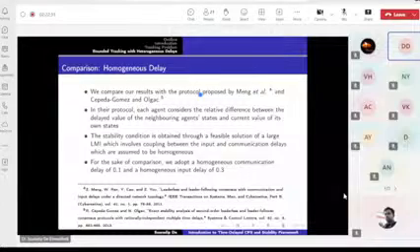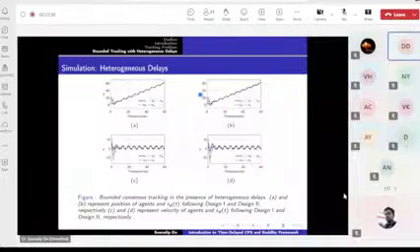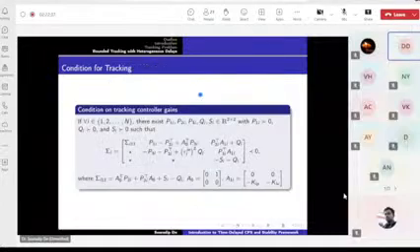So if you go here, what we have done for the LMI in this particular case: you can see here the LMI I am doing is for the tracking controller gains only. For the tracking controller gains, I am considering the individual agents only, not the complete system. Let's say I have these double integrator agents, that means it's a second order system. So I don't have to account for n agents, 20 agents. The advantage of this is that I don't have to deal with big, large LMIs.